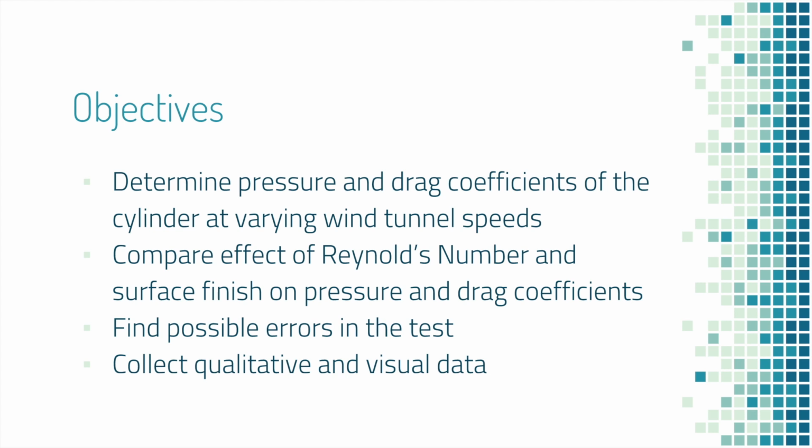Secondly, in this lab, we wanted to explore how Reynolds numbers and surface finish would affect the airflow around the cylinder. By changing the air velocity, we could study the effects of Reynolds number on the flow. In order to evaluate how a rough surface finish might affect flow, we added trip strips made out of sandpaper on the cylinder to trip the boundary layers. Taking data at each speed with and without trip strips, we were able to examine how the boundary layer, vortex shedding, and turbulence changed.